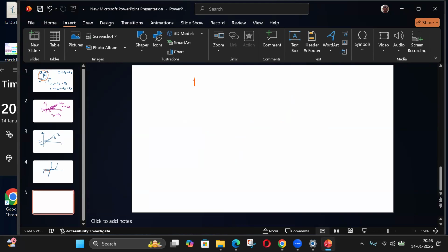Okay, so using that, I can get this relation. Like KCL, I have IE equal to IB plus IC. I've chosen the direction of emitter entering and these two as leaving. And alpha is defined as output by input in the common base mode. And beta is again output by input in the common emitter mode. Output is the collector current.